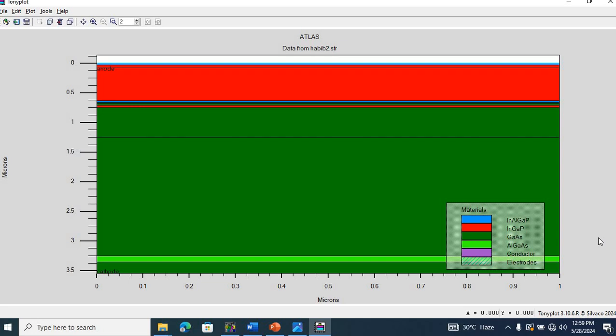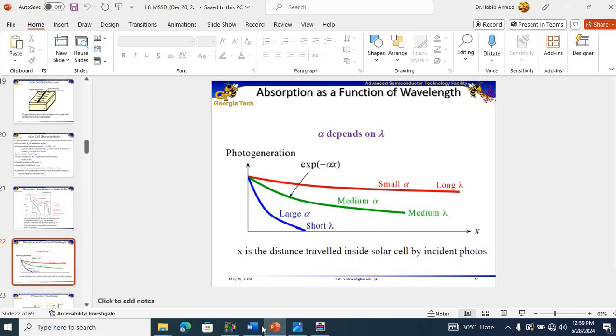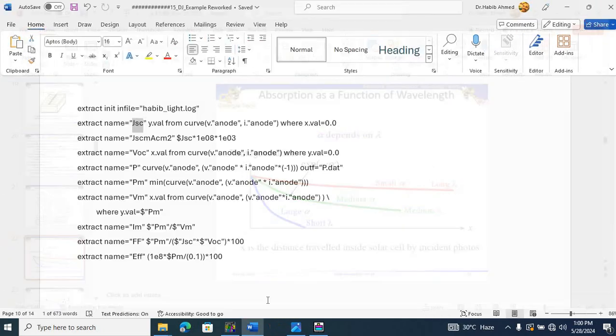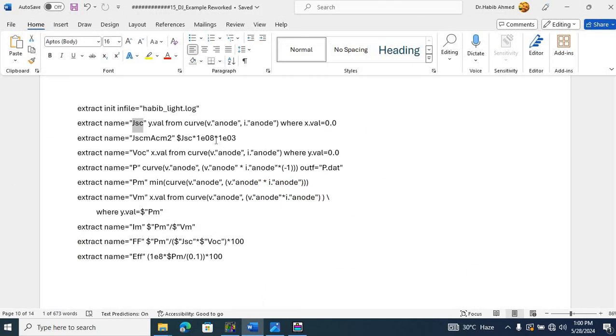And by default, if you don't introduce the thickness of that dimension, Silvaco TCAD sets it to 1 micrometer. So this top surface has a 1 micrometer by 1 micrometer area, and then we convert it to centimeters. Let me close this window. If you want to convert it to centimeters, that would be 10 to the power minus 4 times 10 to the power minus 4 centimeter.